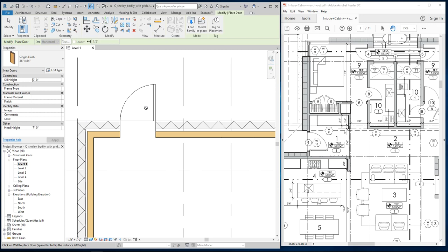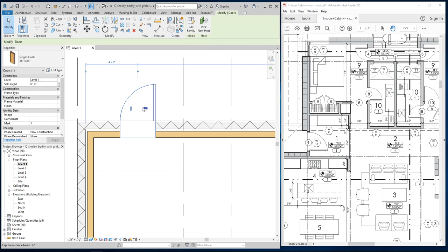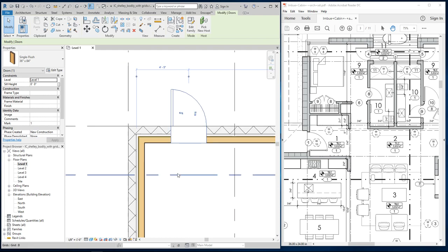And I can change the swing or the orientation of it really easily. So if I click this little guy, it flips, no cleanup necessary. If I click on that, it swings it in, right? Very nice. Do we still have to create the door jambs though? No, nope. Well, let me say, with this door, it's not indicating them, but a lot of the other doors I'm going to show you, I'm going to have you go find. They'll be built into it, essentially. I just wanted to double check because I think yeah, the frame is shown on there. I'm not hugely worried about that right now either, but this door is one of the most fundamental Revit has, but most of the doors that I use at this point have that built into it.